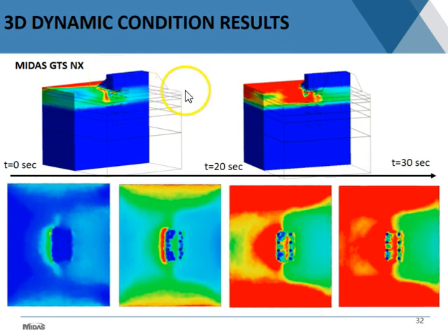And of course, there are some differences because once you turn on the 3D effect, you don't only have displacements along the longitudinal direction of the bridge, but also displacement in the transverse direction. So the displacements are not confined to only occur on the 2D plane, but they can also take place in the other one.